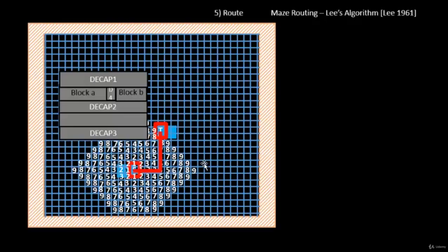Okay, so you can even take this route, and now we have to identify which one should we be picking up. So the difference between this one and this one is that this one has got too many zigzags. It has got two bends, one bend which is over here and the second bend which is over here. Okay, and the other one has got only a single bend. So any route with single bends are mostly preferred in case of a routing algorithm. Okay, so for example, in this case, if there are scenarios where there are no other options, this would be preferred. But since there is an option available of an L-shaped routing, this is being mostly preferred by a routing engine or any routing algorithm.